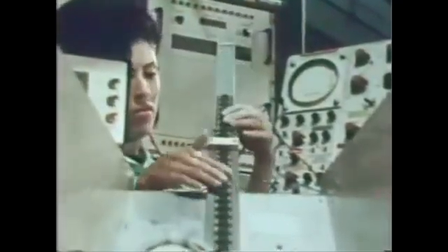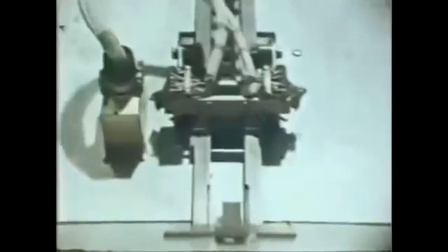Now that the circuit has been packaged, we must again test it substantially before we would dare ship it to the user. First is a series of electrical tests, many of which use special test equipment, which is again built from integrated circuits. Many of the tests made on the integrated circuits now duplicate those tests which were made on the wafers. In addition to these tests which duplicate those which were made before, we must make some special tests, such as frequency response of a linear amplifier or switching speed of a digital circuit, before we would dare ship the unit. We can't make these tests on the wafer state due to the limitations of the test equipment through the probes.